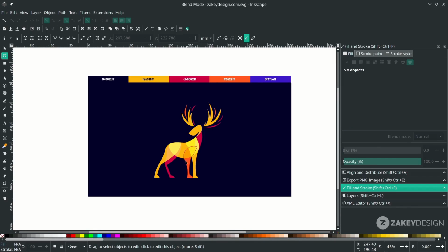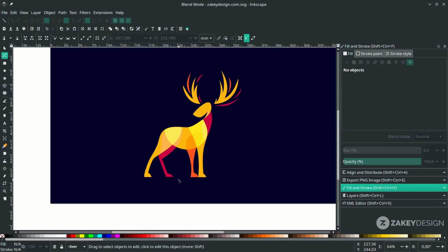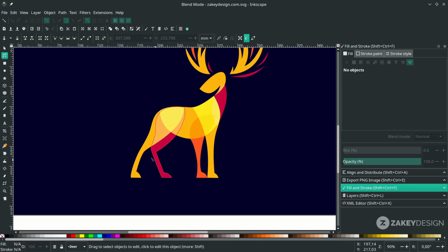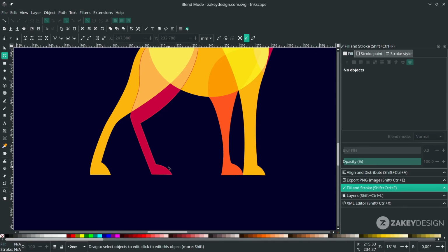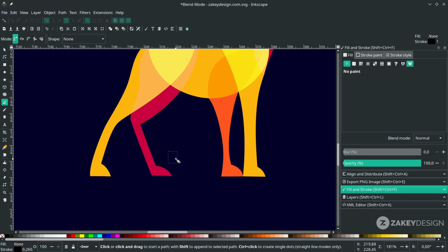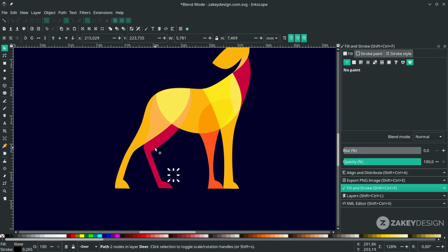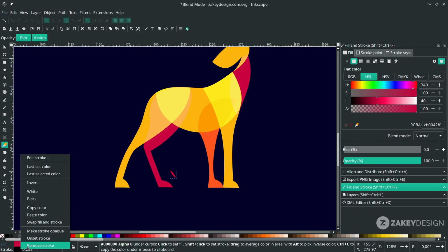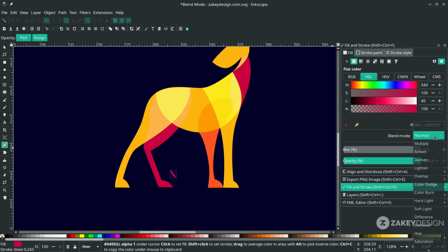Last thing, we're going to create a particle with spray. We're going to create a grass particle in here. First, let's create some shape with the Bezier tool again. Press B and draw some shape like this. Hold Shift to lock the corner and click. Change the color to this color. Remove the stroke and change the blend mode to screen.